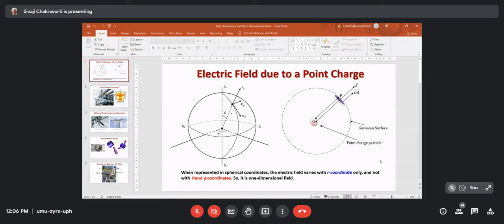We had a lot of discussions and finally they went back. They came back after another month and this time it passed. Then I asked what actually you did finally. They said that they did many things, but finally what they did is that they cleaned this entire transformer winding by hot oil jet. Hot oil jet.